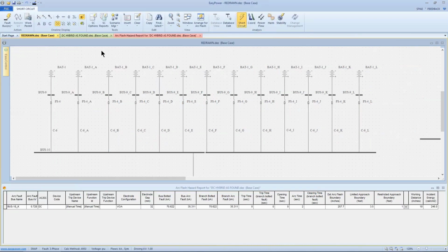And by so doing, now the fuse will protect the fault current coming from that particular battery. So now when I go to short circuit focus and I look at current, if I fault this bus, I still have the 80 some odd thousand amps, but that 6,000 amps now is going through the fuse, and the fuse will protect the bus, and conversely or inversely, the fuse will protect the battery from that upstream fault. So now when we're looking at instant energy and we fault this bus, now we have 6 calorie exposure as opposed to the 800 or 600 some odd before.